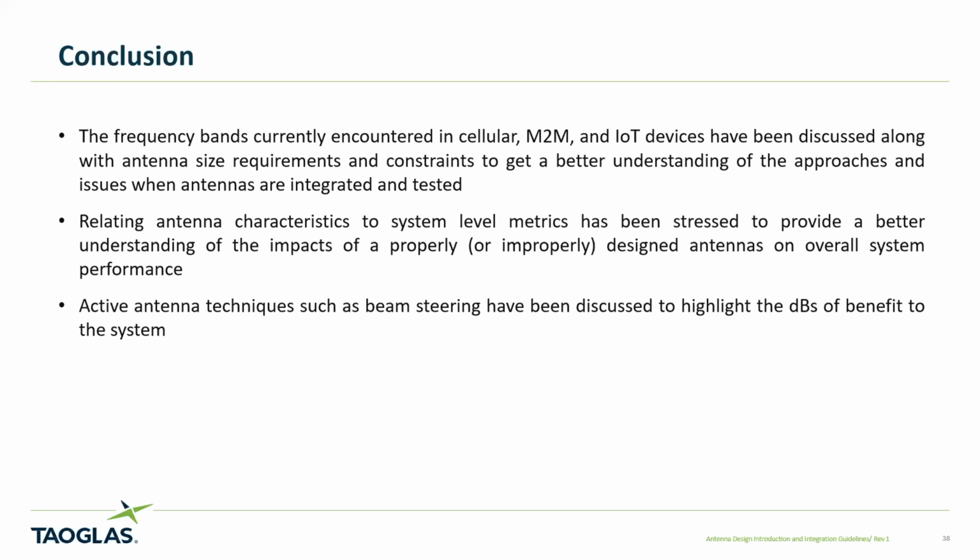I would think interference nulling is going to be pretty prevalent, but that's more for the protocol and the algorithm guys. I would think they'll be implementing nulling, because as it turns out, and we were told many years ago on cellular networks, weak signals are not the problem, it's interference. So when you start talking about SINR, it's not the S you're worried about. You need to worry about the I, the interference, and techniques that can mitigate interference in a cellular network are very good.